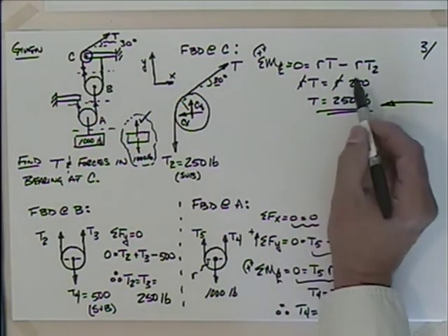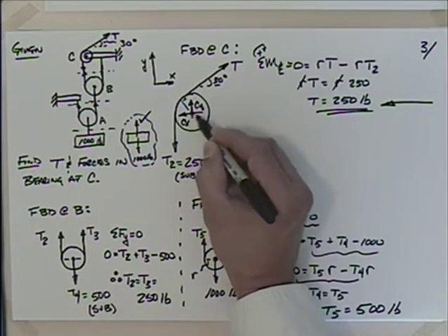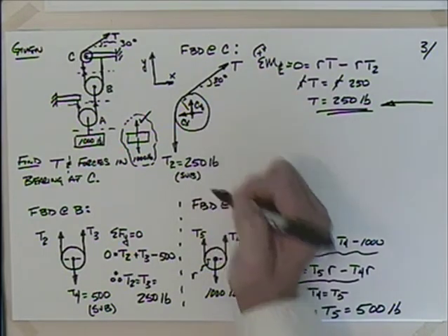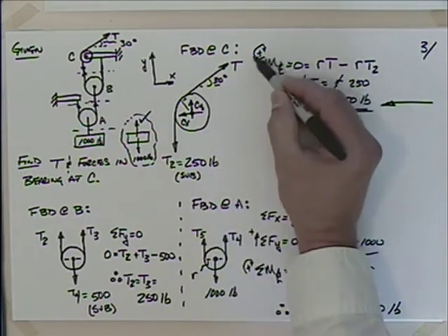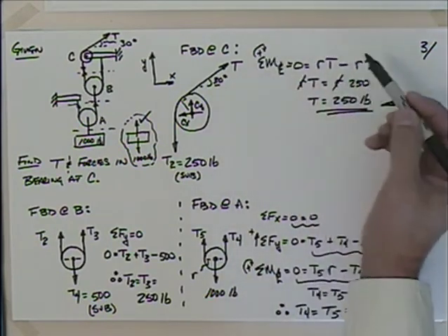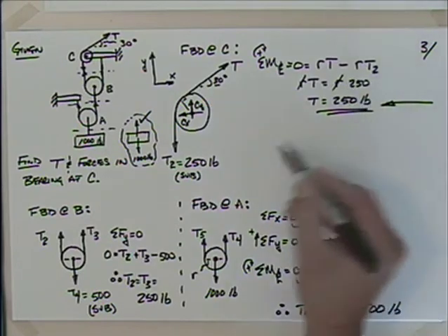Well, that's nice. Why didn't Cx and Cy come into here? Well, remember, I'm summing the moment about this center point here, and those forces intersect that. So that's why they don't play in here. They will in these equations. And again, had you taken counterclockwise as positive, you would have had a negative and a positive, and you'd come up with exactly the same equation and result.